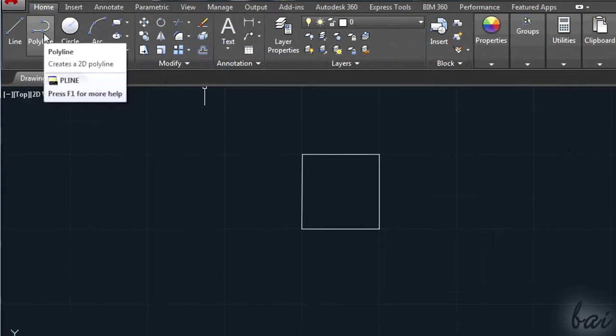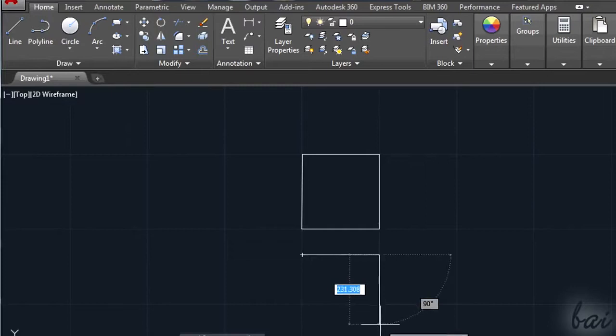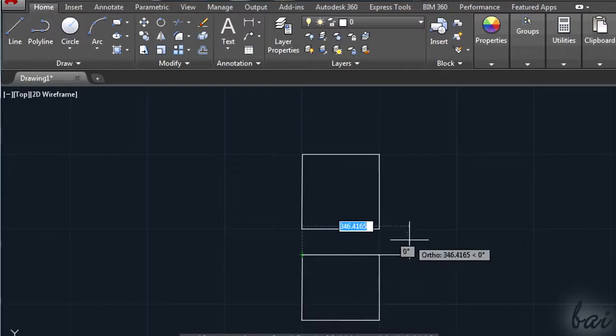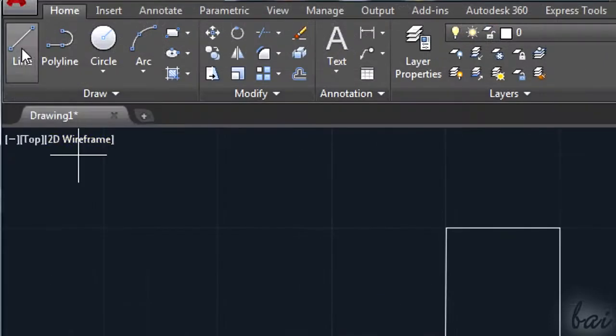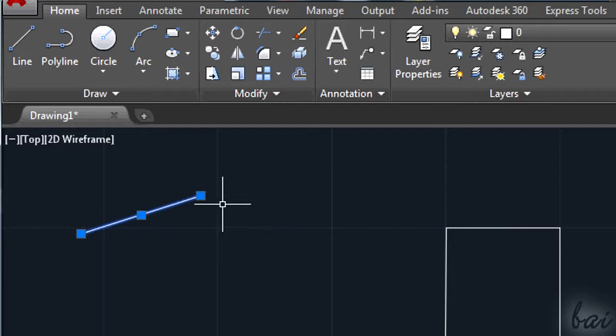Very differently goes when using the polyline. This works just like the line, but if you create a polygon using a polyline, all the segments are managed at the same time. This is indeed a unique object, rather than before with the line tool. Moreover, you can't convert a straight segment into an arc directly.